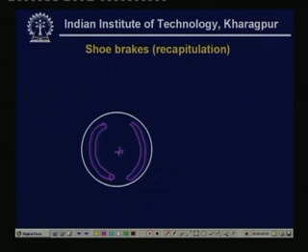so this is the center of the drum, and at a symmetric angle there are two levers, and on them there are these shoes. So, there is friction material, symmetrically placed again. This is an internal radial shoe, and the force is applied here by some mechanism and then these two calipers rotate about these two hinges, and then the friction material gets pressed and it develops the frictional torque.